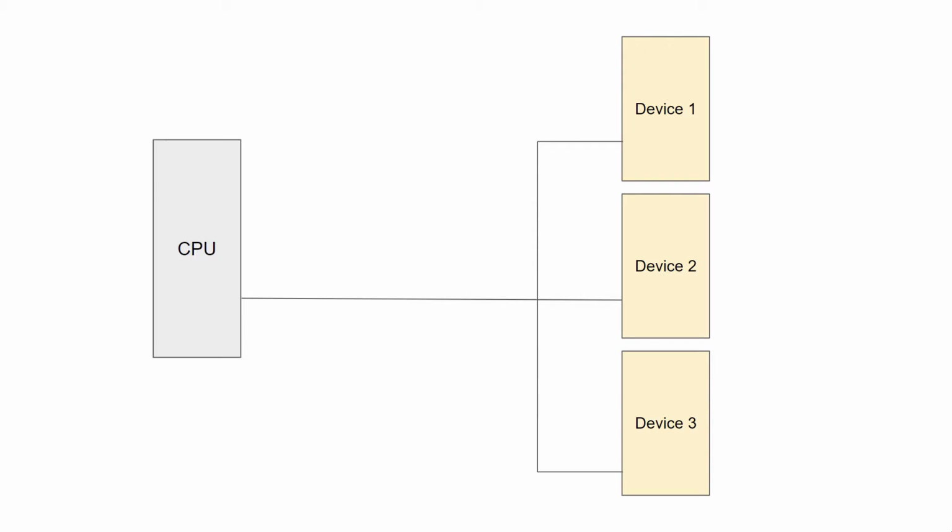Every processor has a means for a device on the bus to let it know that the device needs its attention. It could be a keyboard controller telling the CPU that a key has been pressed, or a communication device receiving some data. It is usually done by activating an input signal of the CPU, usually called interrupt request. In fact, it is usually 2 pins, but we'll get to that in a second.